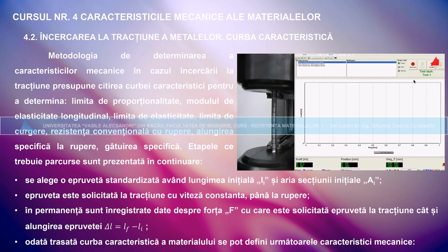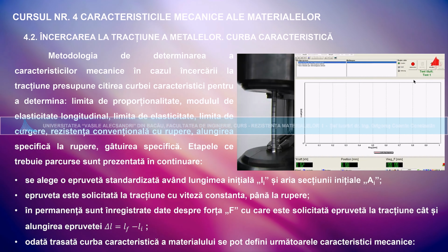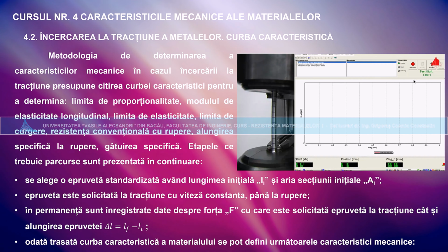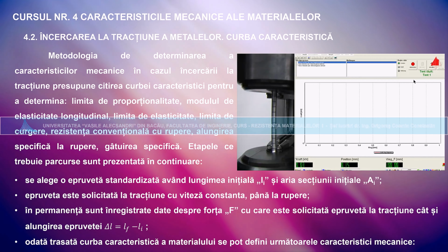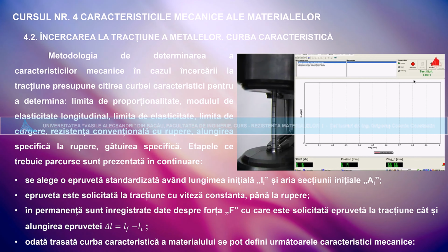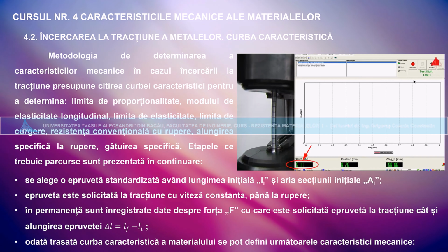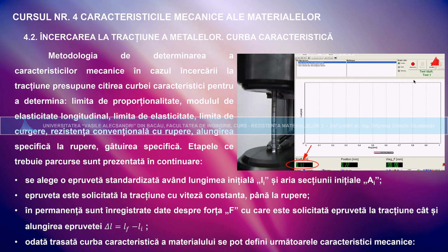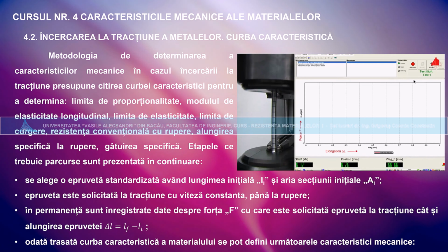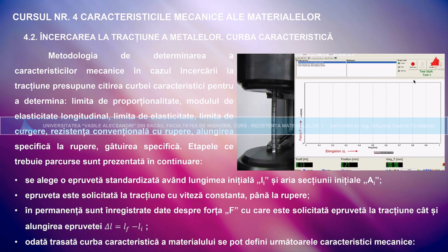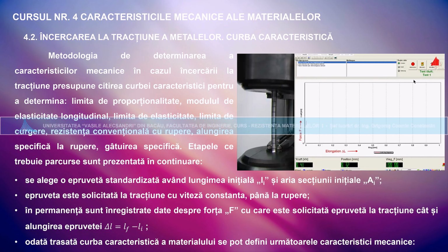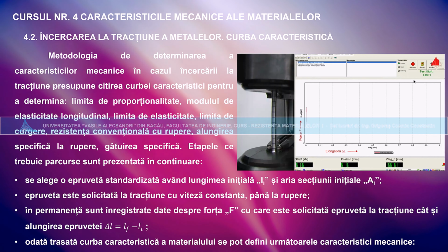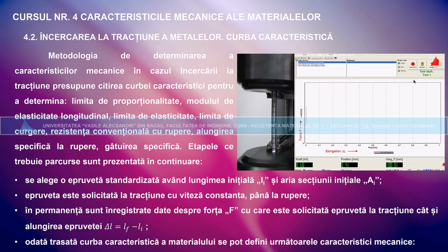During the tensile test, the test piece is slowly and constantly elongated with a standardized speed. The force that the test piece opposes to the imposed elongation is recorded and can be seen at the bottom left-hand corner of the computer display. The material behavior can best be observed in a force elongation diagram. The force F is being plotted upwards on the vertical axis, the elongation delta L towards the right on the horizontal axis.